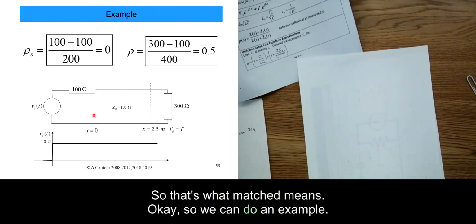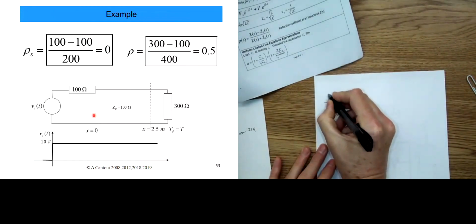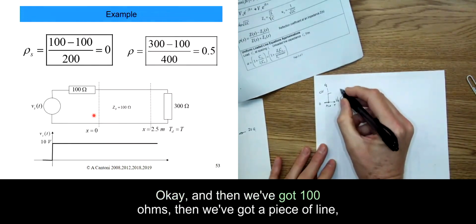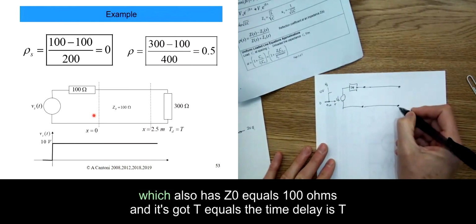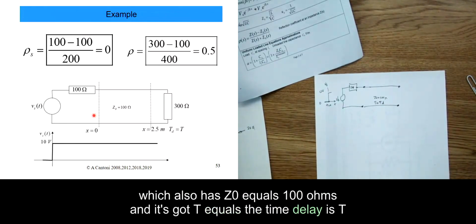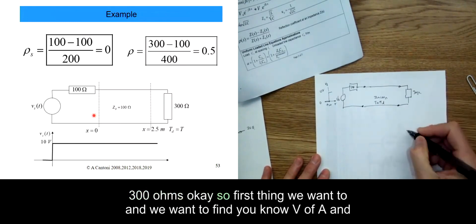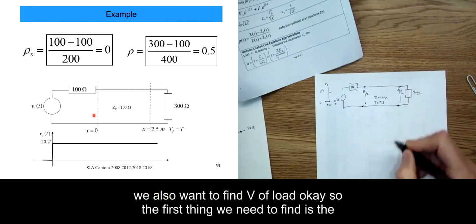Okay, so we can do an example. We've got Vs, a step function. I think it goes from 0 to 10 volts at t equals 0. This is t, this is V of s. Then we've got 100 ohms. Then we've got a piece of line which also has Z0 equals 100 ohms, and the time delay is T. And then we have a load which is 300 ohms. First we want to find V of A, and we also want to find V of load.